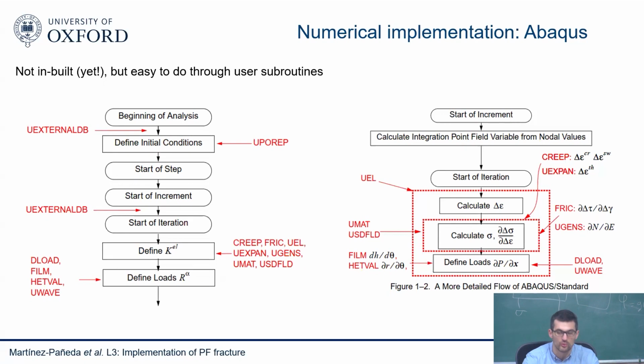So the idea is that Abaqus is a commercial finite element package. It's written in Fortran, but then they have small pieces of Fortran code where they say, okay, as a user, if you want to define something yourself, we let you write it in here. We'll give you what we call a user subroutine, where you receive some inputs, and then you need to do something with those inputs, and then we give you some outputs. So there are multiple ways you can define the subroutine.